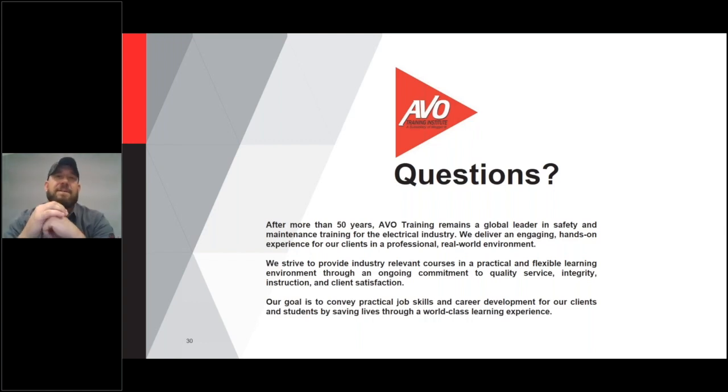There are some companies out there with these vacuum interrupter bottles, and so it's critical that you get into those manufacturers' docs and find out. Some will give a specific value when it comes to contact resistance testing, electrical testing. Some will give a value on how to measure that contact travel, meaning how worn out those contacts are from constant opening, closing, heat generated, and so forth. All right, but it's critical for you to get into the manufacturer's docs when it comes to measuring that erosion several different ways. Nutshell: contact erosion indicator, electrical testing.